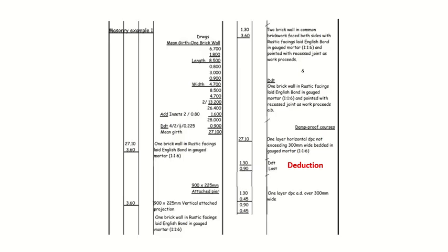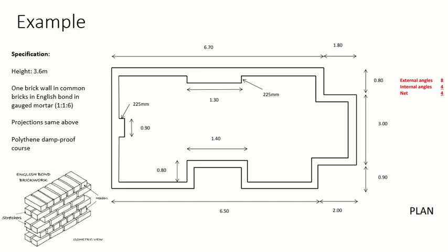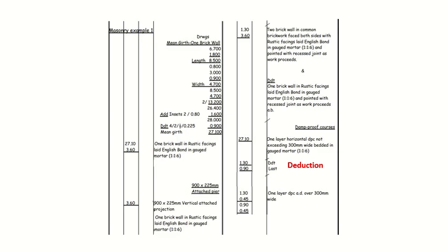And what is this? For the center line. So these dimensions are external dimensions, you can see it here. All of them are external dimensions. So for the center I will subtract. Again the rule: 4 corners, 2 walls, half of the width for the center. 0.225 is the width. So you get the mean girth, which means center line. Another name for the center line is mean girth.